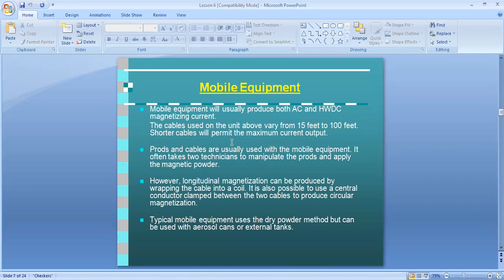So what they are saying means the prod also we can use to generate circular magnetic field, and to generate coil shot also. During the practical, I will show you how we can use the prod machine to generate head shot and coil shot.